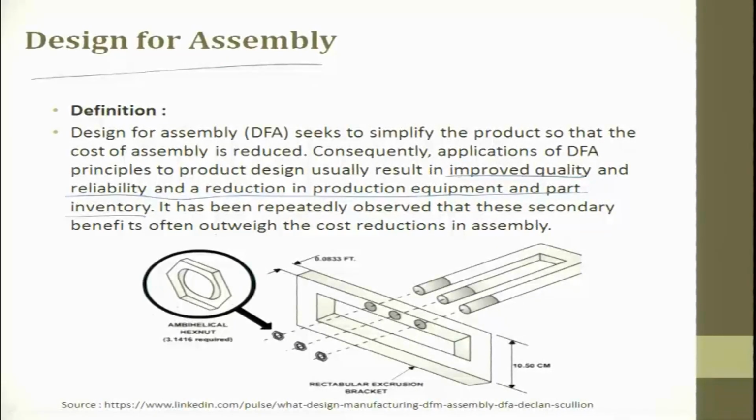For example, you will have a nut, and then you will have a clip which comes and attaches to it. Here is a nut. So, this is pushed, and then here you come and then you will have nuts. Suppose, let us assume, how do you want to follow DFA here. So, instead of having these screws, these hexagonal nuts, see, these hexagonal nuts are always prone to failure. That means it can get unwound and fall down when it is put on dynamic load. So, now what people are suggesting is to try to remove all these hexagonal nuts, and make a thread here.